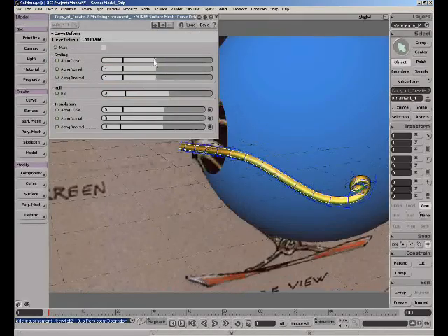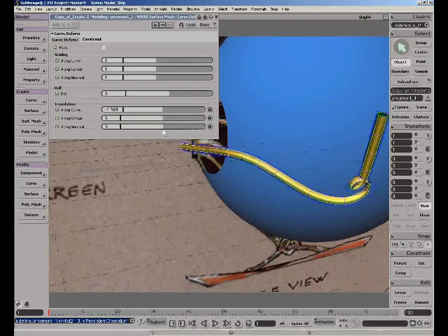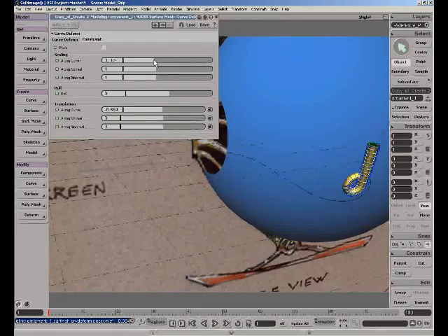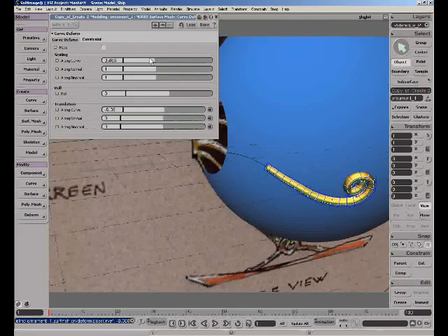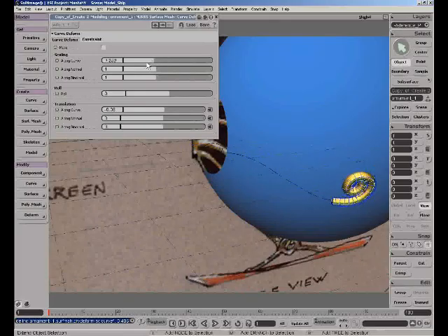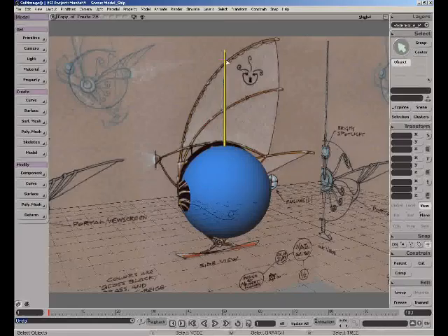We'll frame up here, and let's take a look at the deform tool. Here you can see I have the ability to translate this along the surface of that curve, and I also have the ability to scale it. So what I'm going to do is just simply move this to the end like so, and then use my scaling tool to extrude this out. A nice little thing in XSI is if you ever encounter a slider where you don't really have enough leeway to get the perfect result you want, hold down the shift key and you can see now I can scale this much more slowly. Okay, so now let's go ahead and deform our cylinder along that curve.